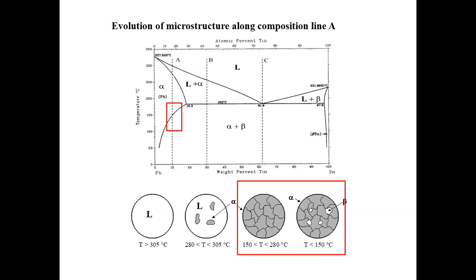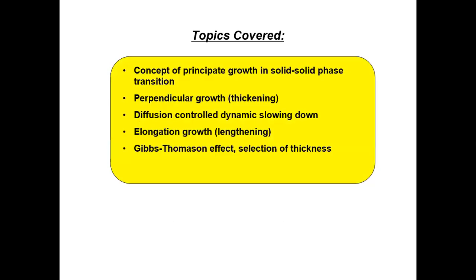for precipitation growth. Okay, so based on this insight, today we're going to discuss the growth of precipitates in solid-solid phase transformation. Because we already came to the conclusion that grain boundary nucleation, the heterogeneous nucleation on the grain boundary, is much more frequent and is the dominant mechanism for the transformation, we will just focus on this particular mechanism. We will not go back and talk about the growth of the homogeneous nuclei, right? Because we see from the previous image that they usually are very small, do not grow a lot, and in terms of numbers, these nuclei are much rarer to see.